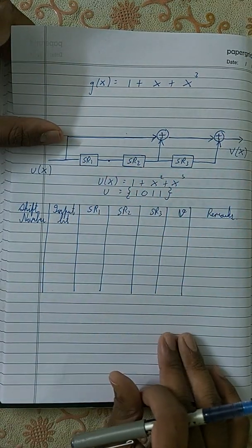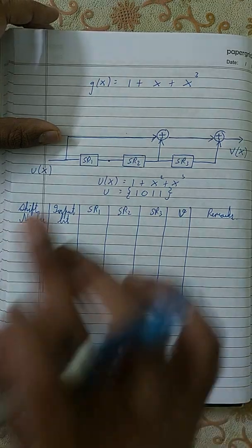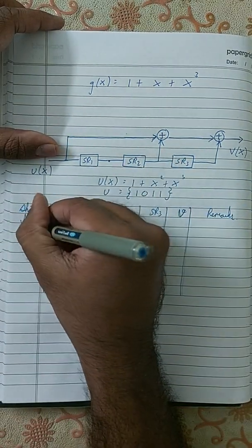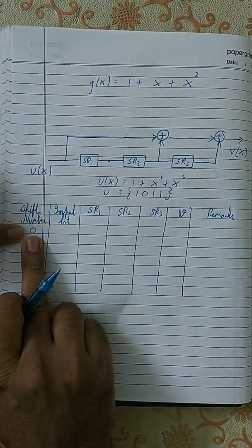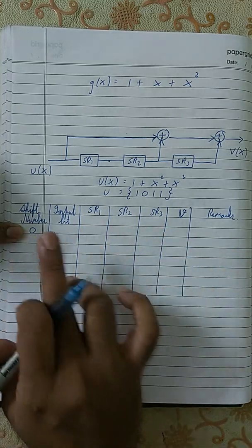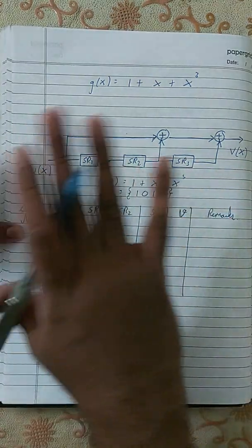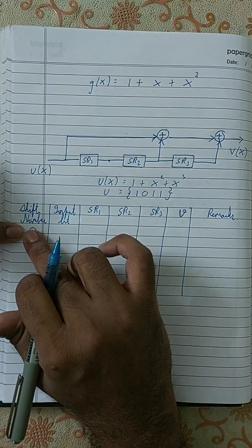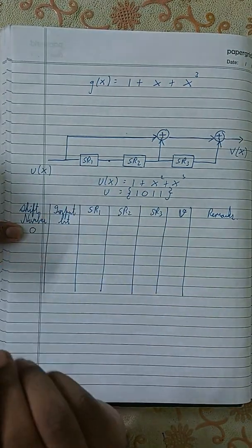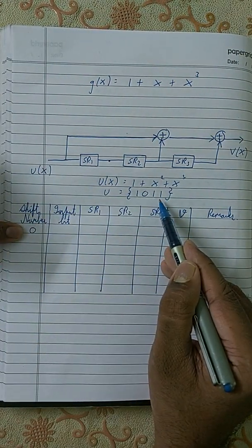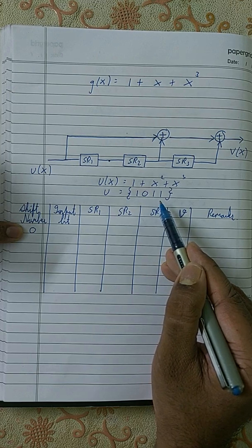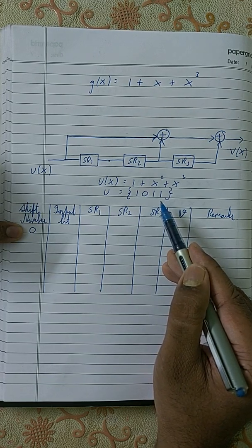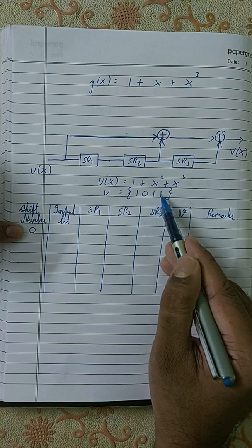the remaining answers. So in the first clock cycle, on the 0th number, before sending the clock cycle, we don't do any shifting operation, and you just simply place the bit over here. The first bit will always be, like I said before, the bit of the highest order coefficient, which is this one over here.